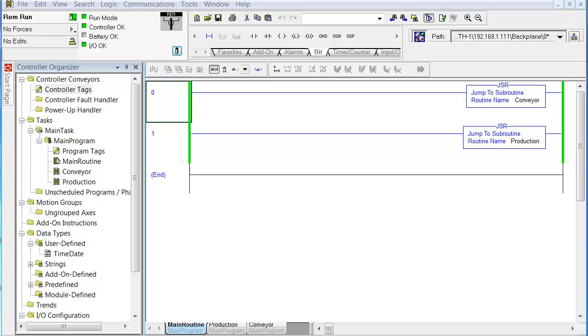You knew up front that you had several of these process buffer conveyors installed. Why do more than one and then have to debug more than one? Do one, get it right, and then copy your work. You went out and you commissioned the first conveyor section on the shop floor, the plant floor, and once you had it working perfect, then you came back, sat down at your desk, and now you're going to do the following procedure. So we're going to save our program always.